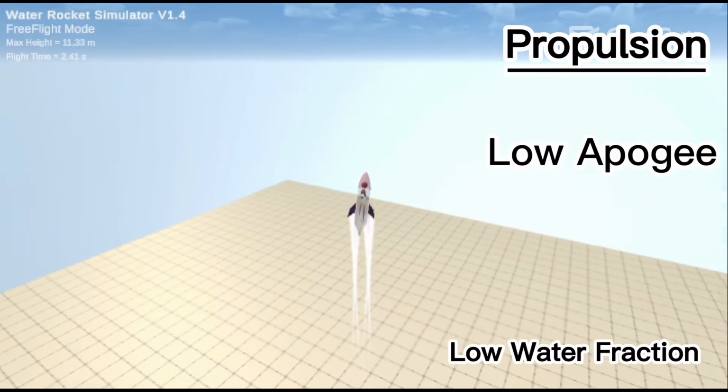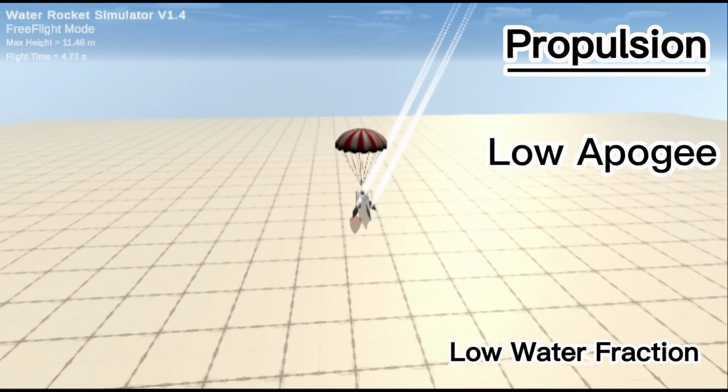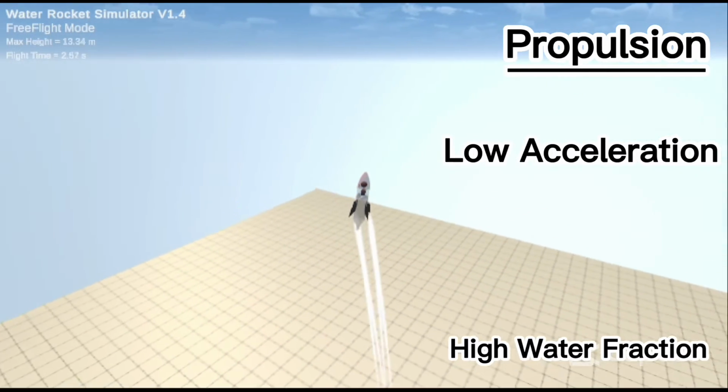If the water fraction is too small, there will be a relatively small mass, meaning a smaller impulse, causing there to be less thrust. If the water fraction is too big, then the relative mass of the rocket is also too big for significant acceleration at launch, where thrust is highest.